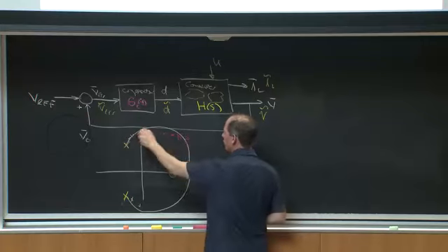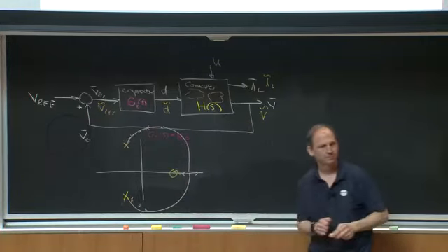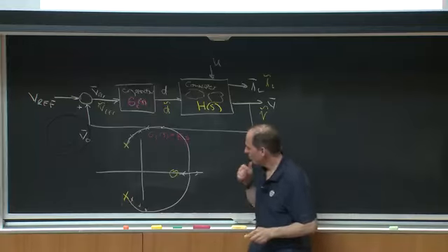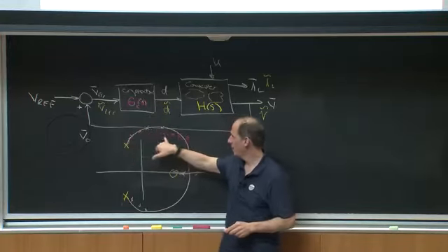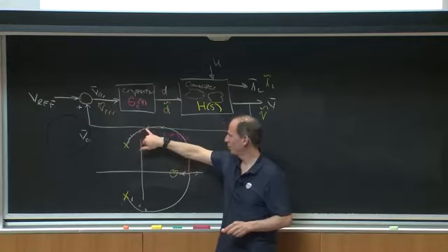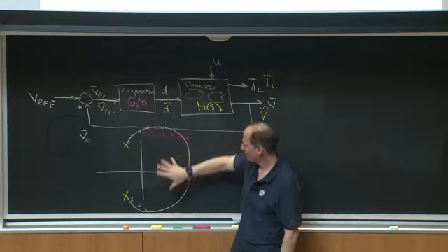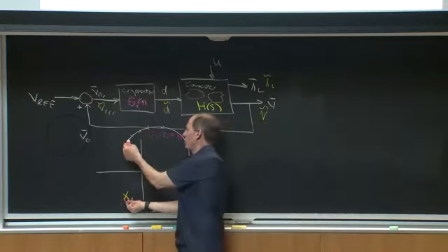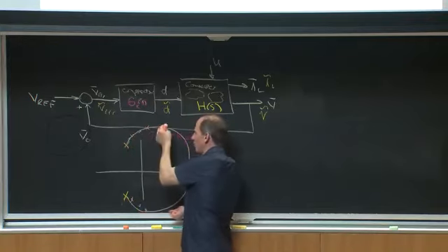And so these are for different values of KP. Okay? So that's kind of a problem because I want a high KP because I want the error to be small, but if I make KP too big, once that pole moves to the right half plane, this whole thing's going to oscillate, right? So this is the nasty thing about the right half plane 0, is that the closed loop values will be moved from where the open loop poles are somewhere into the right half plane.